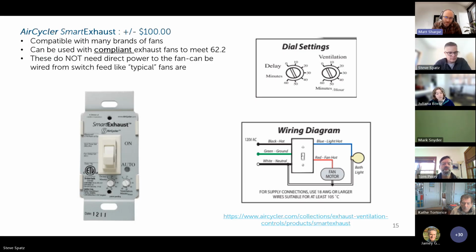Now, what you might come into is if you have your light wired to come on when the fan comes on, right, you might not be able to avoid that with the existing wiring unless you rewire it to be separate. Gotcha. Okay, so the simplest way to put it in would be to just assume that when the fan's on, the light's going to be on. And then you probably don't need to add another wire.